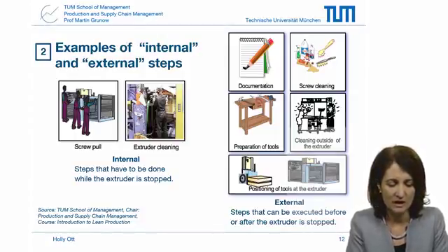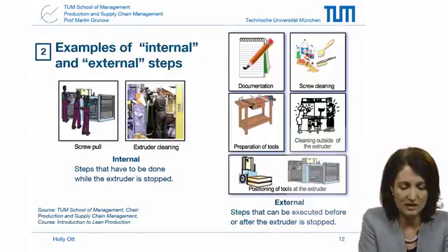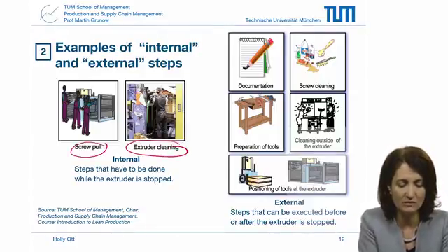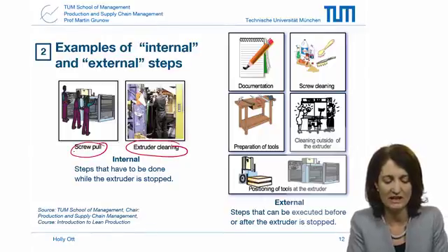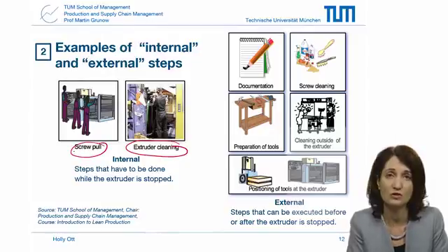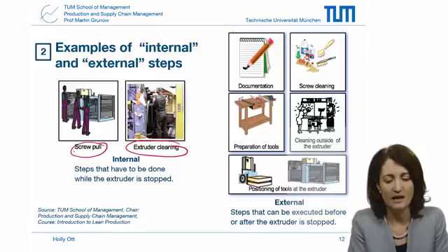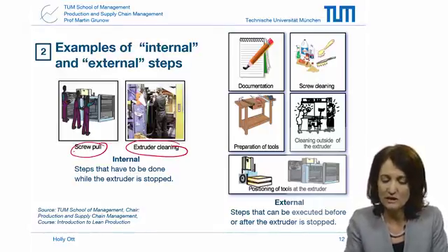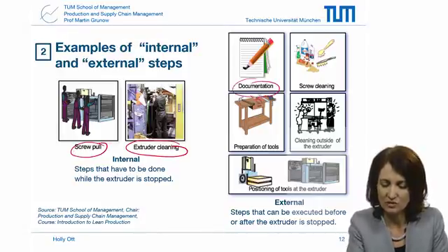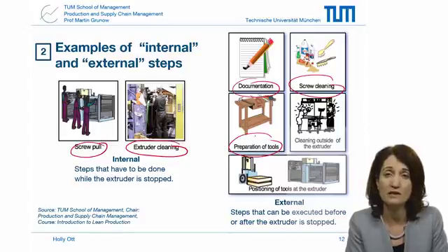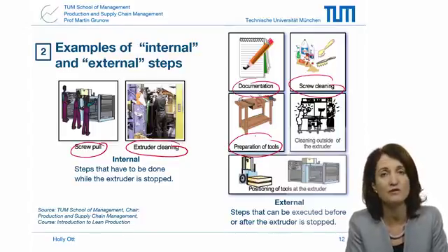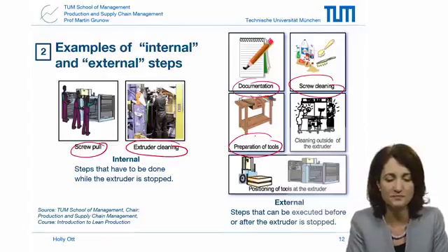And you could have steps such as extruder cleaning or some type of screw changing that has to be done internally, while the extruder is stopped. Those are steps that cannot be done as preparation, and of course they're taking away from your productive time at the extruder. But we were saying things like documentation or certain types of cleaning or tool preparation can be done while the extruder is working.